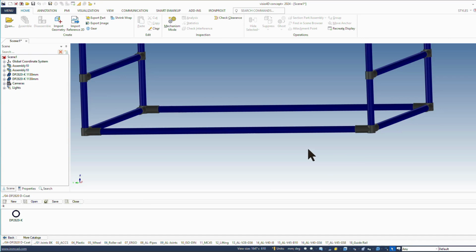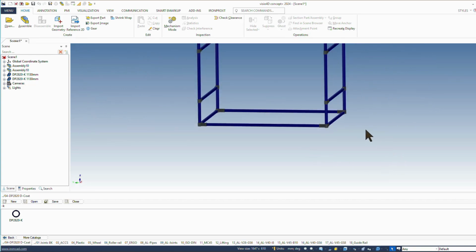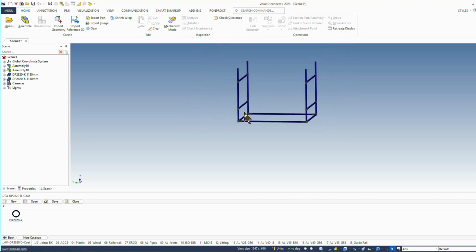I can see it straight away when I look at the measurement. The 1130, that's a straight measurement. That's always a sort of personal check. If, in principle, both perpendicular pipes have a straight dimension, then the pipes must also have a straight dimension. That means that when I draw up a parts list at the end and look at the pipes, then all the pipes, apart from perhaps the diagonals, should actually have a straight dimension, provided I've designed it correctly.